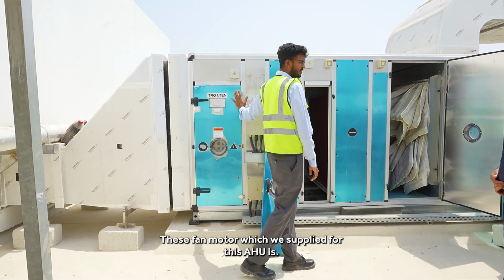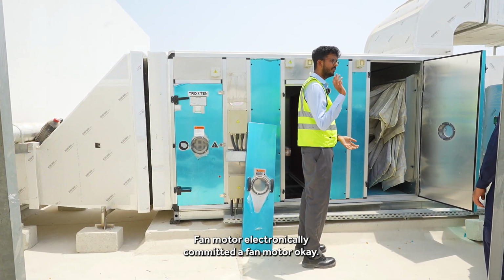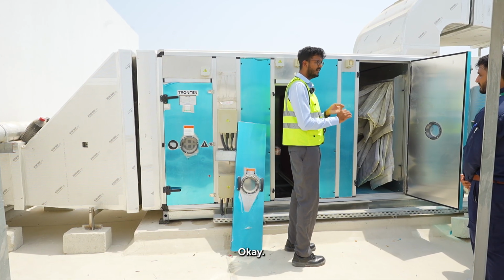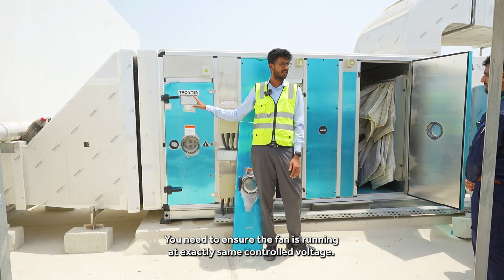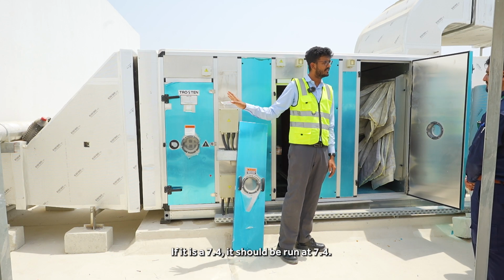Okay, the fan motor which we supplied for this AHU is an EC fan motor, an electronically commutated fan motor. The purpose is to provide high efficiency, redundancy and noise reduction. These fans were selected for a certain control voltage. You need to ensure the fan is running at exactly the same control voltage. It should not exceed the control voltage. If it is 7.4, it should be run at 7.4.